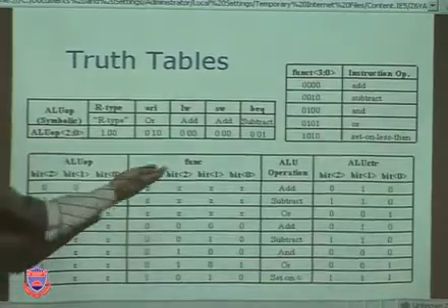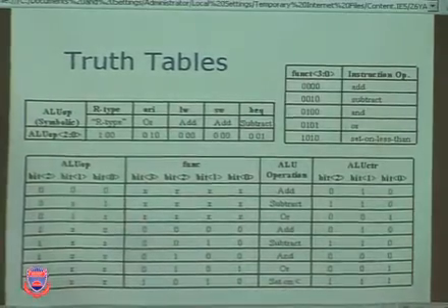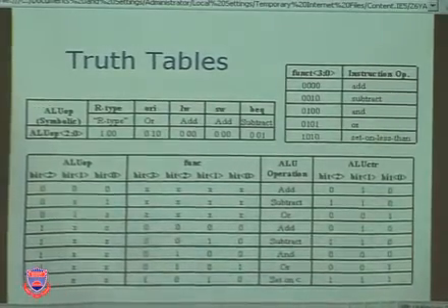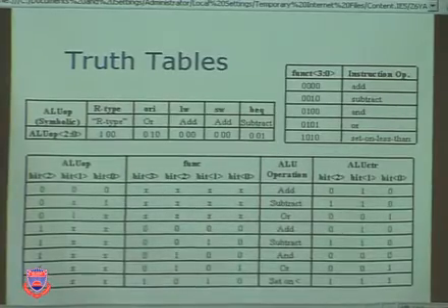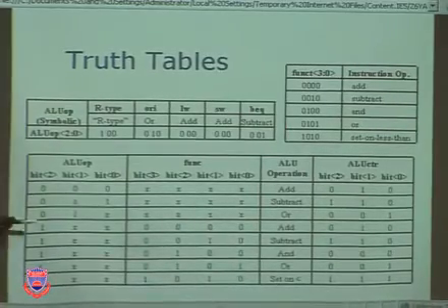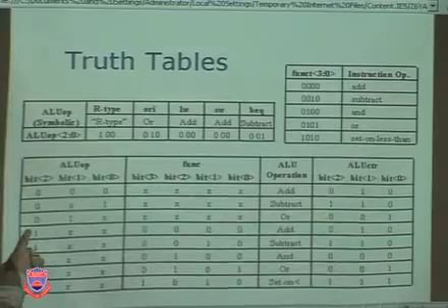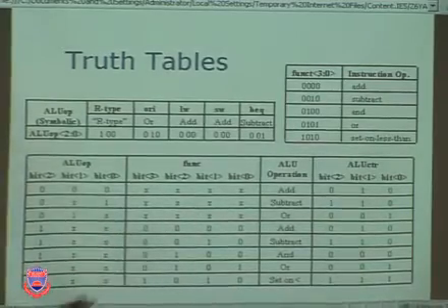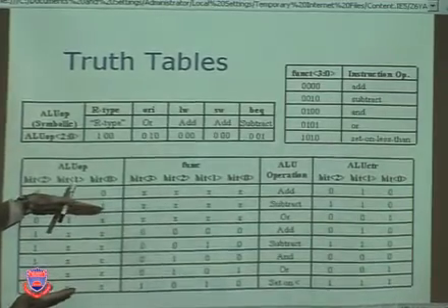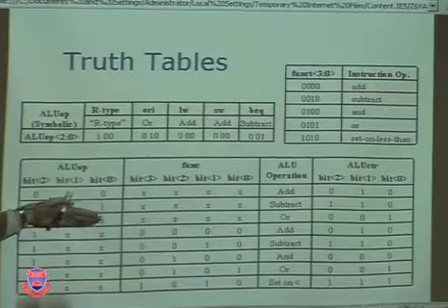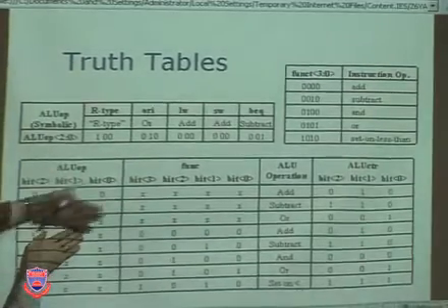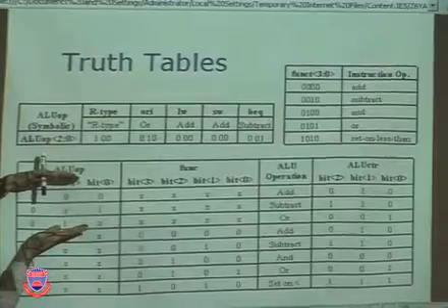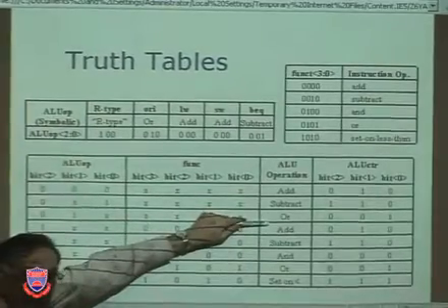Now, when does this matter, these function bits? When do the function bits make a difference to me? Yeah, when I have an R-type. And so the code for R-type is 100. But since I don't have any other codes beginning with 1, all the 100s can become 1XX. So here this means R-type, and that means this matters. This means not R-type, that means this doesn't matter. So these 3 are doing add, subtract, and OR.